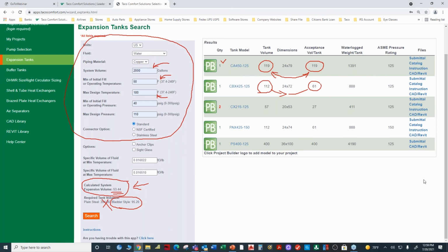Someone might build and fill a chilled water system before putting it into service in a building. They might have everything finished, 100% buttoned up, ready to go, except they're not going to start the chiller. So it's going to just sit there initially with 50-degree water in it. It might sit there through a very hot period in the summertime, in which case the ambient temperature could get over 100 degrees. And if the chillers aren't running, the water temperature would cause the fluid to expand. I guess there were some records set in Nevada that I was reading about this summer, like over 120 degrees. So for a chilled water system, I typically pick the maximum temperature at about 110 degrees.